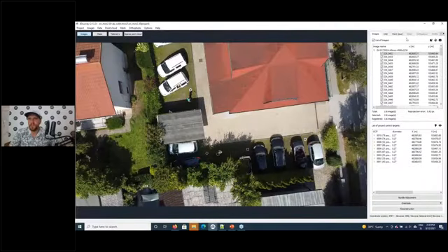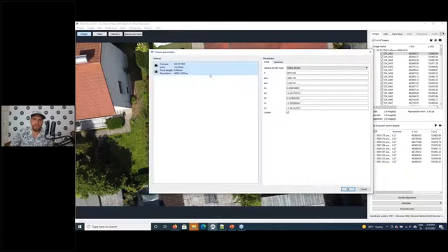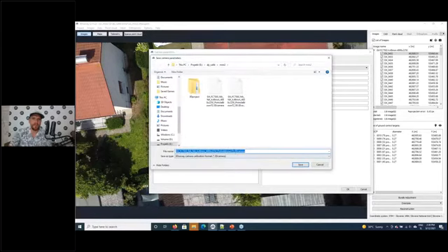at this point, we would again calculate the point cloud, make sure that the point cloud is accurate. So here, the best way to check that the resulting point cloud is accurate is to either check some point with your total station or GPS measurement, or add some other data, like for example, LiDAR, if you have that available. If the point cloud turns out to be good, go here, save the parameters. You can write here the date.